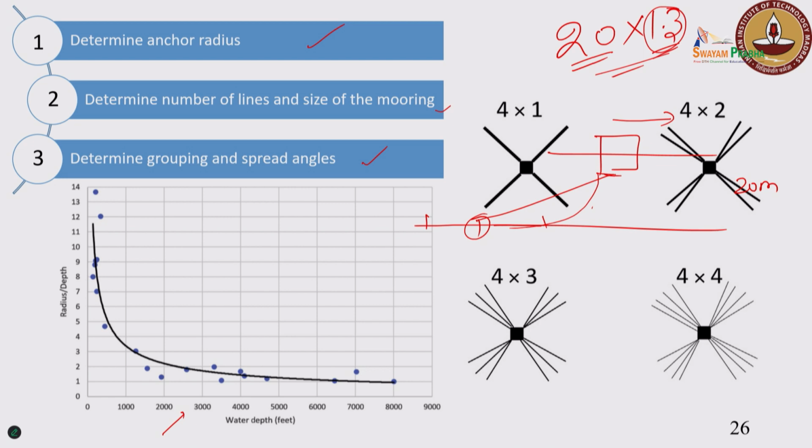So again, depending on the type of anchor you choose, some anchors are primarily meant to take both the horizontal and vertical loads, that is okay. But depending on the type of anchors, for example drag embedment anchors or pile anchors, all these things have an impact on the other. If you start designing one, it will have an added advantage on the other, or one will have a negative impact on the other, so you need to make a good trade-off between the different items.